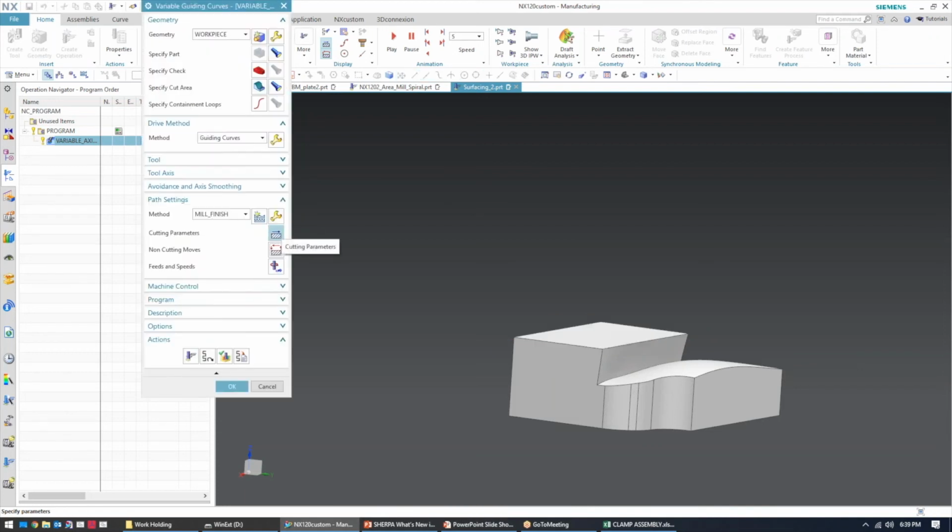But one thing I have noticed is that the guide curves, especially, really limit that sawtoothing action. You really don't see it to the extent that you're used to. Like I said, I've only seen it on really bad imported surfaces. It was just horrible. It translated over really poorly, and that's the only time I really saw sawtoothing with guide curves.